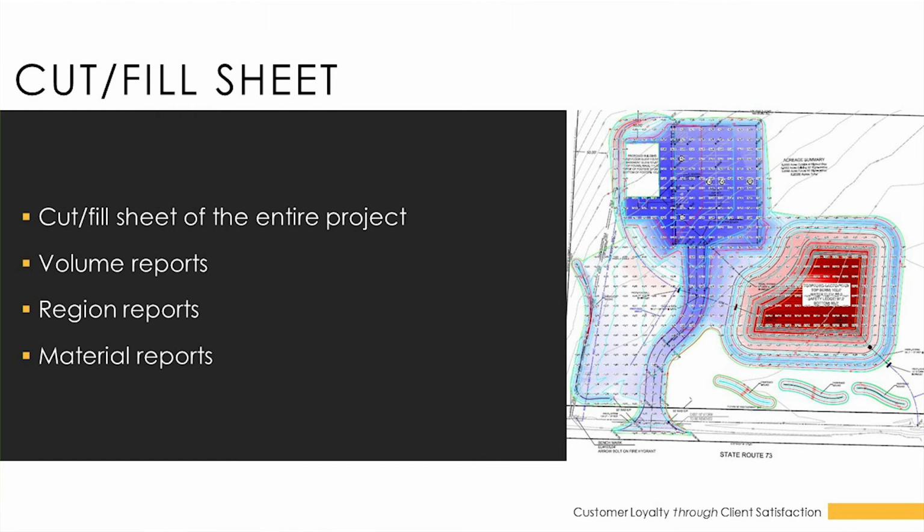Cut fill labels can be prepared from the original surface, or from the top of the clay or rock being the calculated surface after all the topsoil stripping and excess burden have been removed. Then we compare it to the proposed finished grade or the calculated subgrade surface. It varies as to which one you want to go with, for different reasons. We would prepare the subgrade surface based off the typical sections of the proposed imported materials.